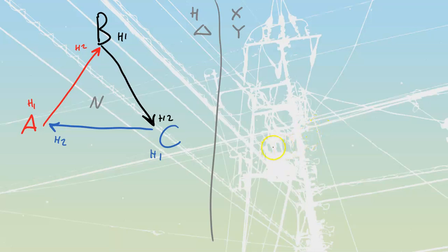We know that initially on our high voltage side, we had an A to neutral that was 30 degrees off, but now we have to move this thing up by 30 degrees. So our new location for A is actually going to be up here. Actually, I wanted to go with my red marker and right away mark that in as being a red A. So we know where that A is, we know where our neutral is, and then we know that the rest of these marks, B and C, are just going to be rotated around here. A to B to C, going around like that.